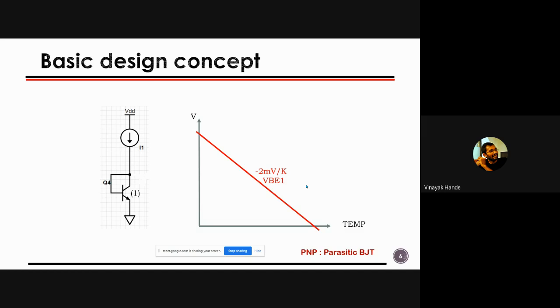Because they are much more concerned about the transistor or CMOS performance rather than the parasitic BJT performance, because the parasitic BJT is generally used for a voltage reference only. And as a voltage reference is generally considered a DC circuit, people don't bother to put in extra effort when fabricating the PNP in the foundry, right?